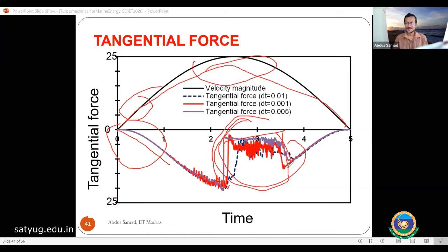The Indonesian aircraft plunged because this flow separation occurred and they got very low lift. Torque is lift, actually. So they plunged into the ocean. Here also, in the turbine case, we saw this phenomenon in our simulation. If we can reduce this flow separation area, or increase this smaller area, in both cases we can get a better turbine and better power from the ocean.